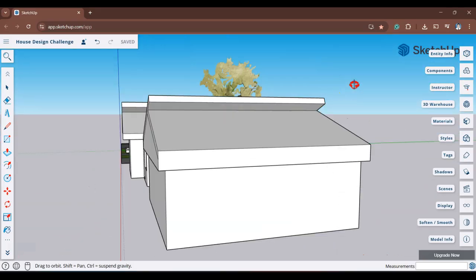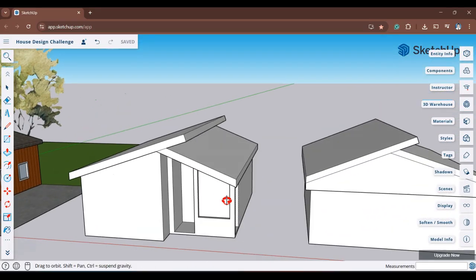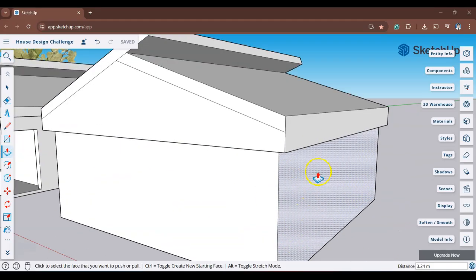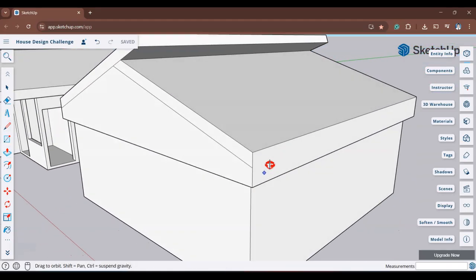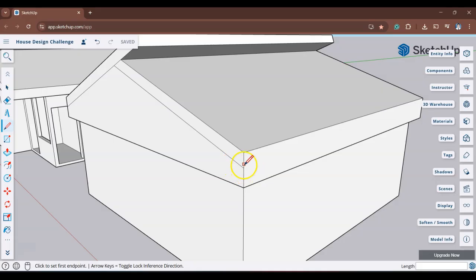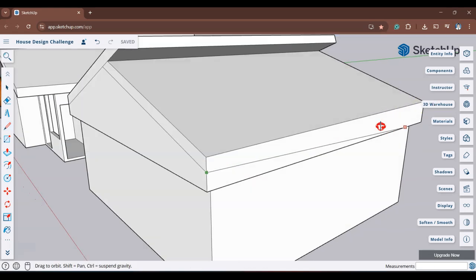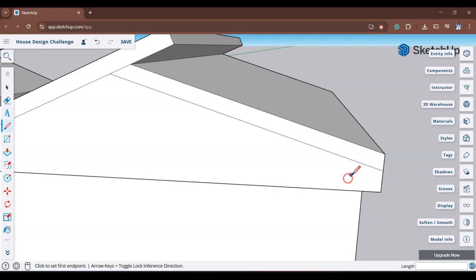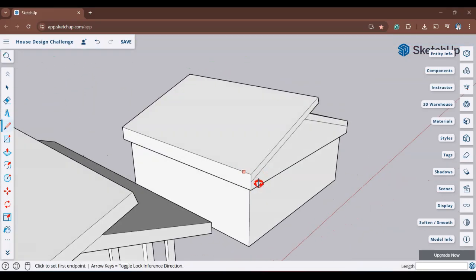All right, so this is where the video tutorial I provided before kind of loses me. This is what I would do better. I'm going to press L for line. And right here where that edge connects, I'm going to click that. And I'm going to draw a line all the way to this edge right here. And then I'm going to just rotate, repeat on this side. Click and go to right there.